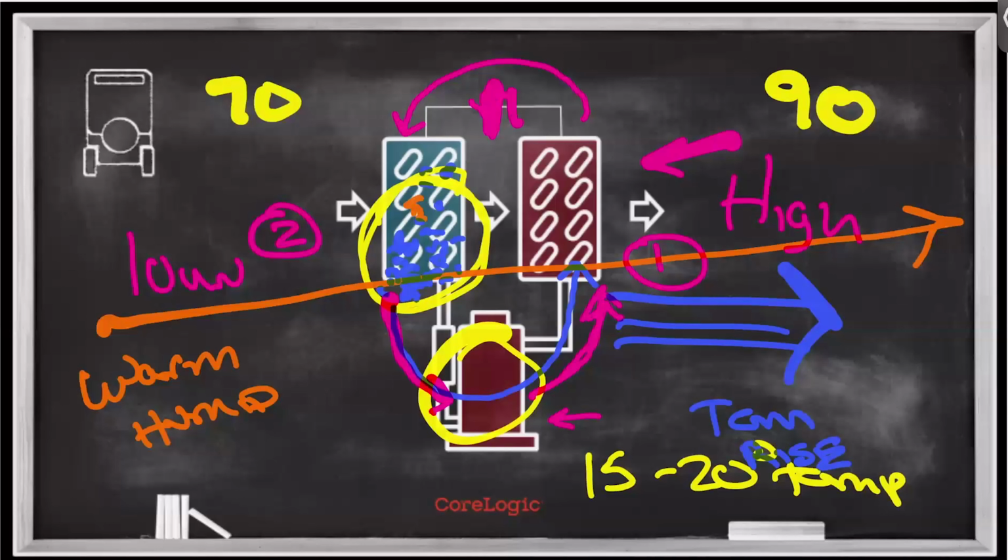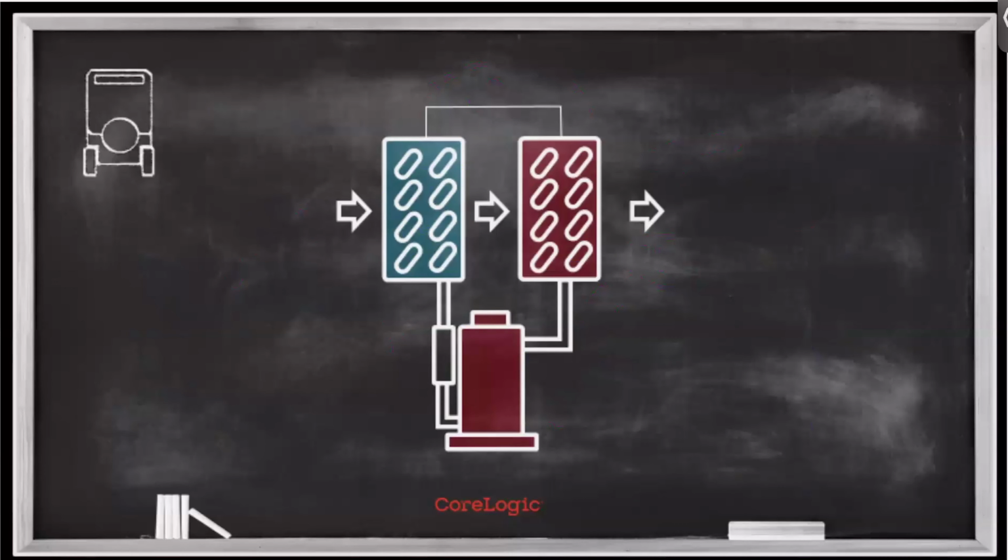All right. So now next, let's take a look at the other way that we commonly measure the performance on these dehumidifiers for humidity control. The other way that we measure these is through something called grain depression, right? And grain depression is a measurement of the humidity of the air entering the dehumidifier versus the humidity leaving. For example, if the air entering the dehumidifier is 80 degrees Fahrenheit at 60% relative humidity, right? Then we can take a look at that measurement and we can say, okay, how much moisture is actually entering